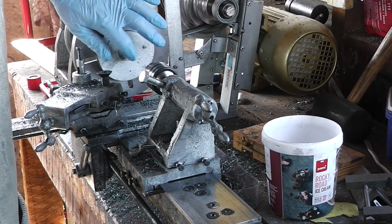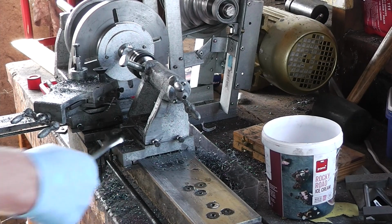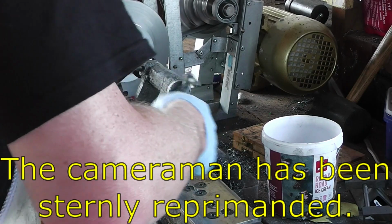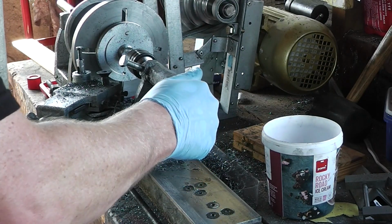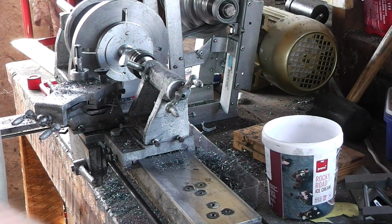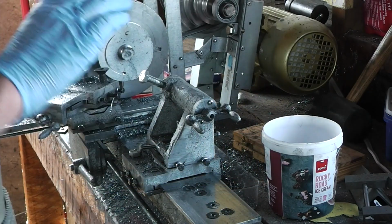Going to drill a hole in this for the centre, or I should say for the bolt that will be the axle to go through. Lock the carriage, lock the tailstock down. I'm not drilling the entire way through because there's still the spindle nose on the other side and I don't want to hit it. And that's that ejected.